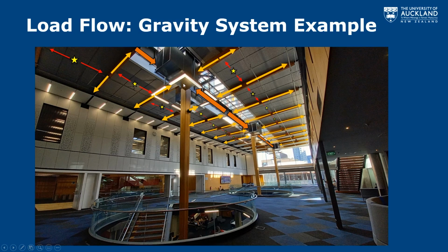And that support is really on top of these columns. And that means that we'll take that load down to the ground. So all of a sudden, we've worked out what our load path is. It will be from our sheathing and our purlins out to our secondary beams, from our secondary beams to our primary, from the primary to the column here.